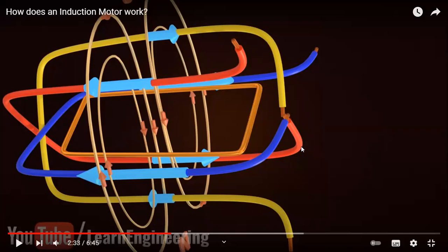After putting the 3 phase supply here, a magnetic field is created, and the nature of the magnetic field is rotating. The speed of the rotating magnetic field we call the synchronous speed. After that we put a coil, represented as an armature or rotor, in the magnetic field. According to Faraday's electromagnetic law, when we put the coil conductor in the rotating magnetic field, one EMF is generated.